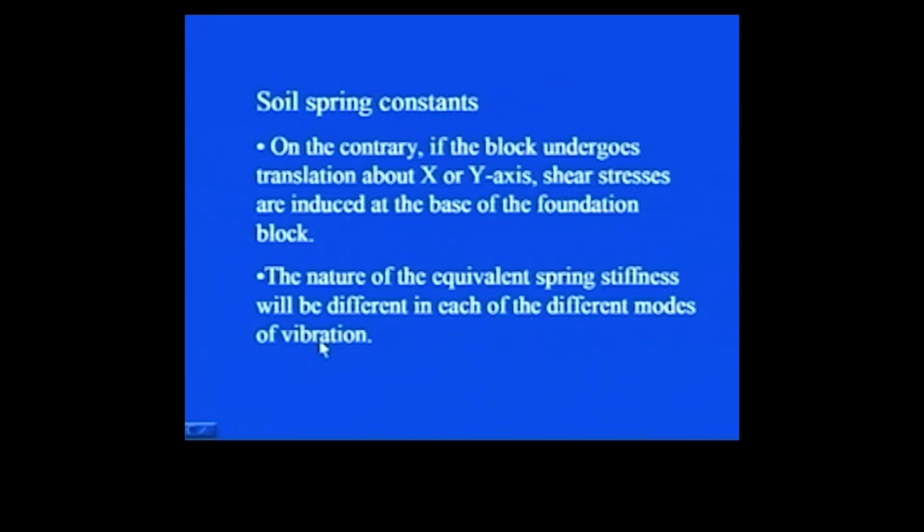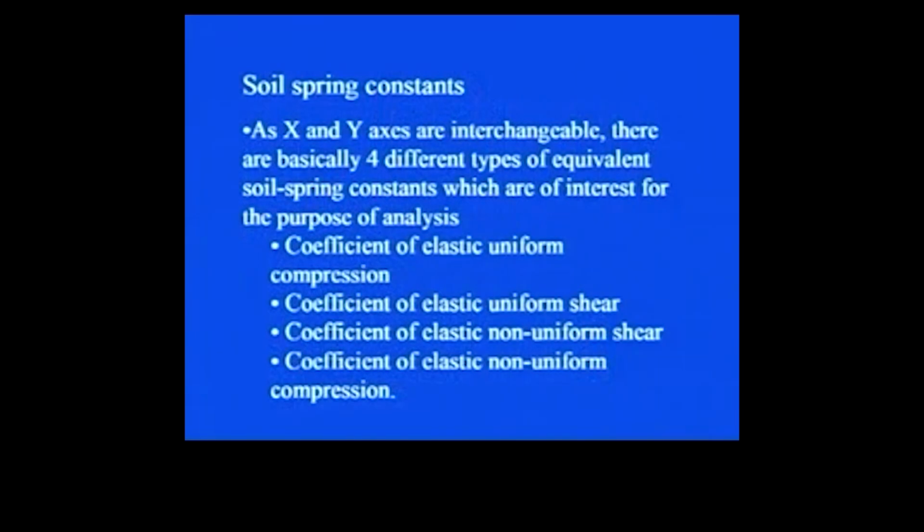Obviously, when it is subjected to compression at the base of the footing, the property of the soil, or the equivalent spring with which you have replaced the soil, will be different, and in case translation is taking place, the spring constant will be different. As x and y axes are interchangeable, there are basically 4 different types of equivalent soil spring constants which are of interest for the purpose of analysis.